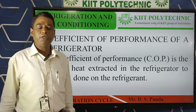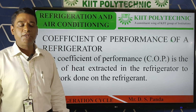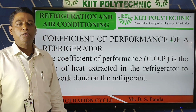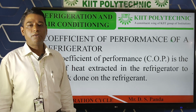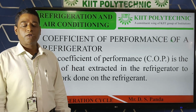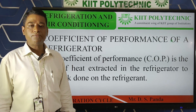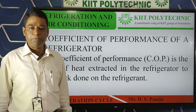Next is the coefficient of performance of the refrigerator. If we think about the refrigerator, the coefficient of performance is the ratio of heat extraction capacity to the work done on the refrigerant. What amount of heat is extracted in the refrigerator, relative to what amount of work input is given to the refrigerant.